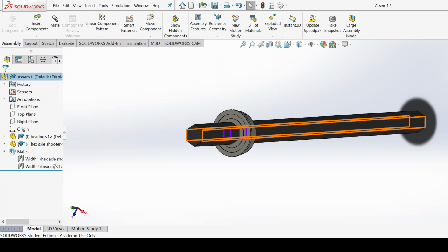So as you look here, as you see which parts have mated together, I selected 2 parts which are opposite to each other. 2 purple rectangles selected first, and that's of the bearing, and then I selected the 2 same parts for the axle. And I did that twice. A key reminder is you have to have them be adjacent to each other. So you see this purple rectangle has to be adjacent to this upper rectangle.